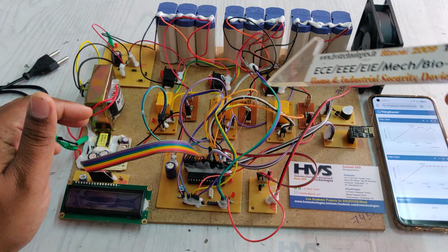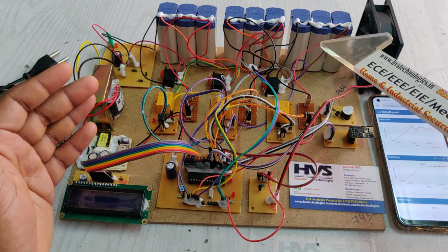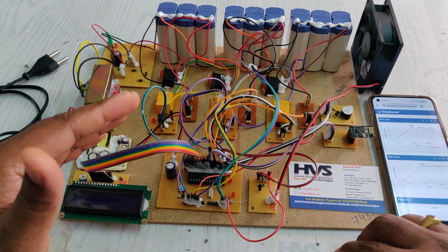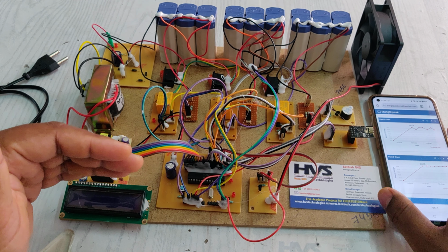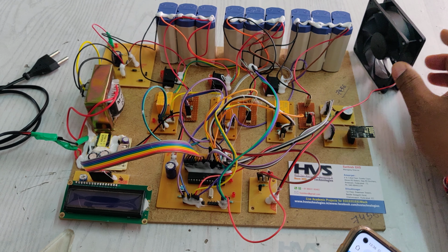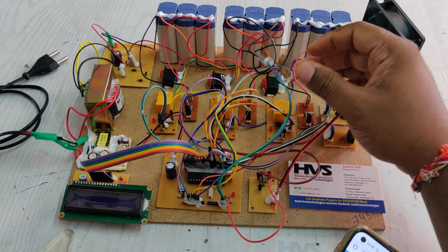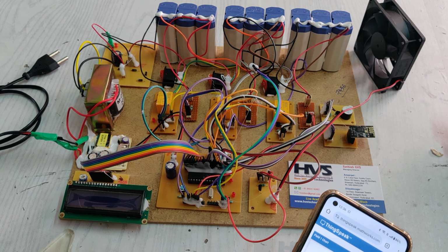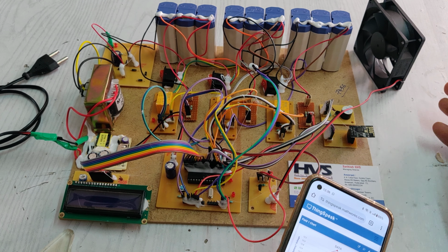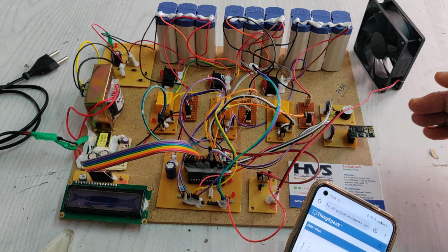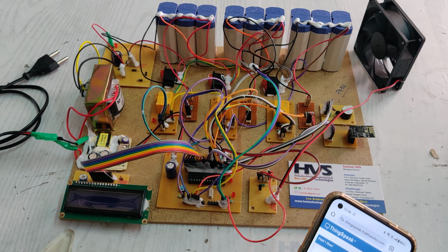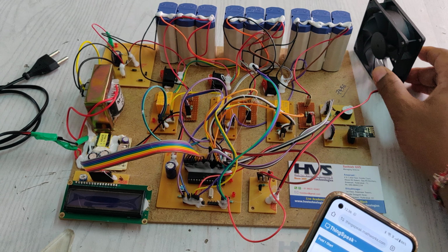With the help of these relays, we transfer the voltage between these battery packs, and this is the main application. And continuously the battery voltages along with SOC, SOH and temperature are monitored, and we also have thermal protection using this temperature sensor. Whenever the temperature exceeds 45 degrees centigrade, so we set that 45 degrees centigrade. In real time it may depend on the battery pack. If we use lithium ion, that would be around 90 degrees, like that. So we can set it for temperature protection, thermal protection purpose.